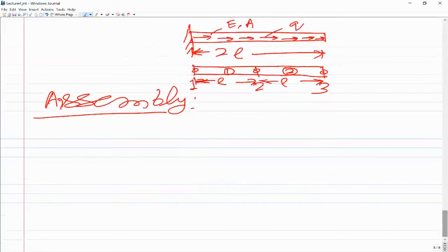So at node 1 you have the displacement u1, and at node 2 you have displacement u2, which is the same for the second node of element 1 and the first node of element 2. The u is the same. That is how the continuity of u is enforced. And at node number 3 you have the displacement u3. So before imposing the boundary conditions, you will have three displacement unknowns, u1, u2 and u3. So the overall size of my stiffness matrix will be 3 by 3.